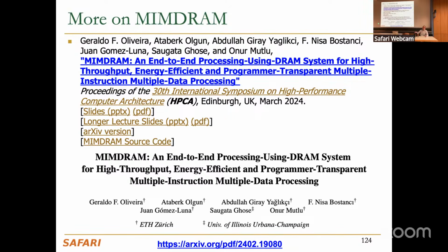Yeah. So we're going to look at that when we talk about processing near memory. Processing using memory is something we're focusing on today. But when we get to processing near memory, we'll discuss 3D stacked architectures. There needs to be more done in that domain, but all of these ideas are applicable to HBM as well. Because if you look at HBM, DDR, they're all internally the same. The array is the same in DRAM. So you can do all of these in HBM, plus you can do more because you have 3D stack connections across the memory arrays as well as the logic layer.